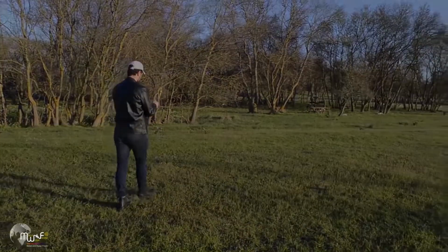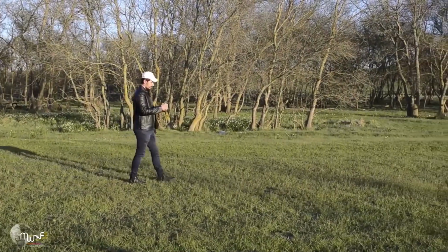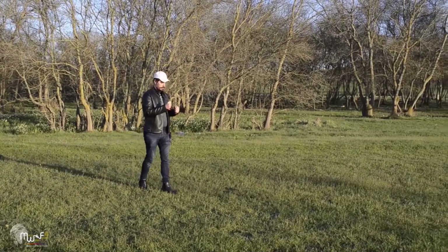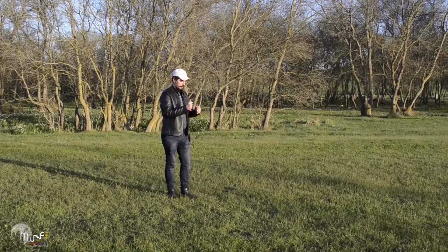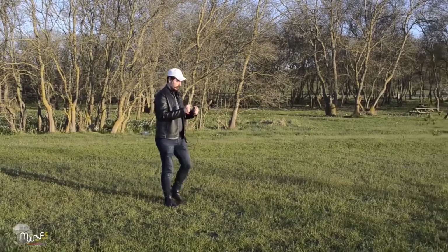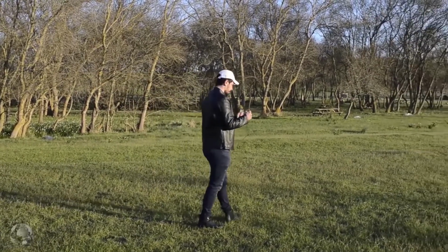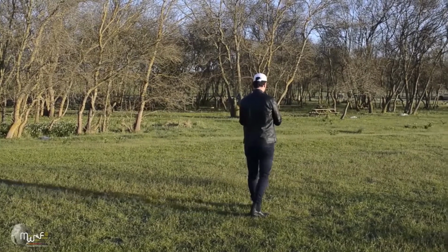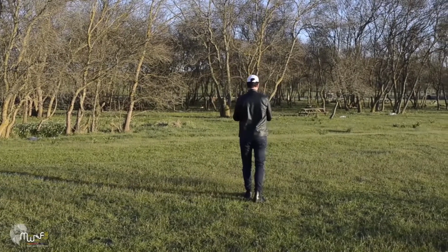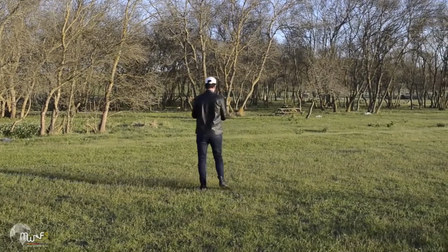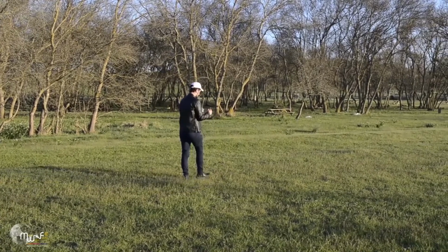Follow this line by walking in a zigzag way. The antennas open and diverge when outside of the power line field and intersect completely when passing over the power line again. Continue this way to track the power line to reach the target location.